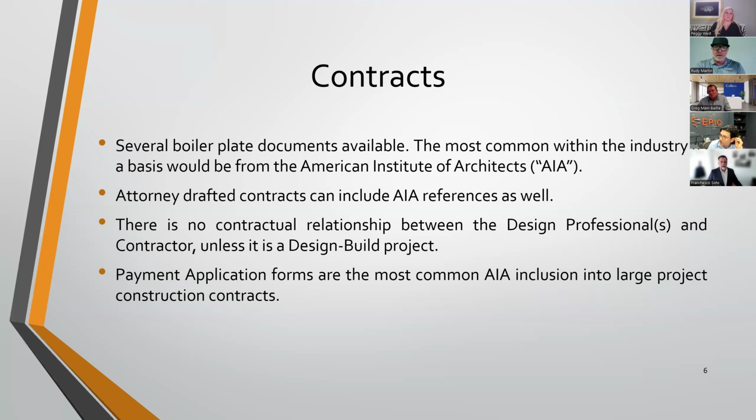Yeah, and one thing also that the contract will stipulate, amongst the several details, is going to be retainage. We'll talk more about what retainage is and its purpose once we get later into the presentation. But identifying the amount of money that should be taken out on each pay app is going to be critical. So remember, if we're talking about planning, and not wanting to think as much during the course of construction and minimizing those variables, the contract is going to be the finality of that planning phase, right?